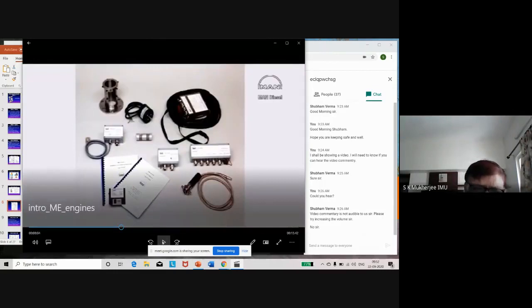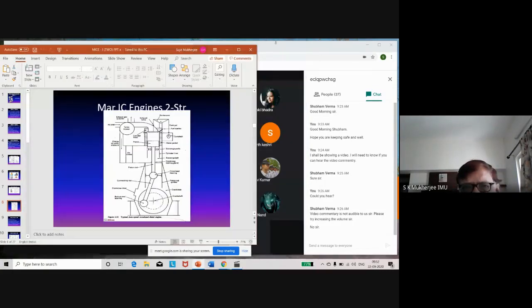Okay, now this is going into our 6th semester area. So we will put a stop to this, and that is what you have seen of a two-stroke engine and how the parts are working. That was my intention, to show you how this engine is working. You saw how the crosshead functions moving up and down, and it enables the connecting rod to swivel and at the same time rotate at the bottom portion.